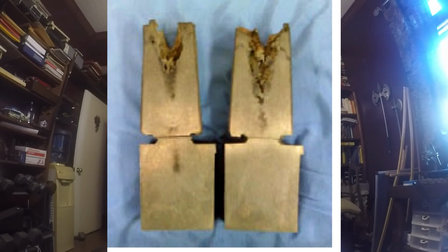Now, another thing I can see is that these must have been two different castings, because the one on the right is good, but the one on the left shows something of a defect. See that brown smudge, what appears to be a smudge in the bottom of the casting, or rather the casting portion below the riser? That is not solid metal.